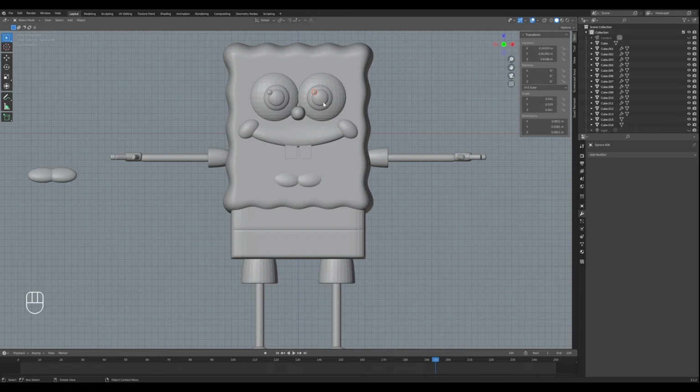And then there's another little white dot right here on this eyeball. So select. Yeah, I guess we can select both of these. Shift D, move it down, move it over, and then scale. You know what? We're going to do one. Actually, yeah, go ahead and scale. Because these are going to be smaller than these, right? Okay. Let's move one at a time.